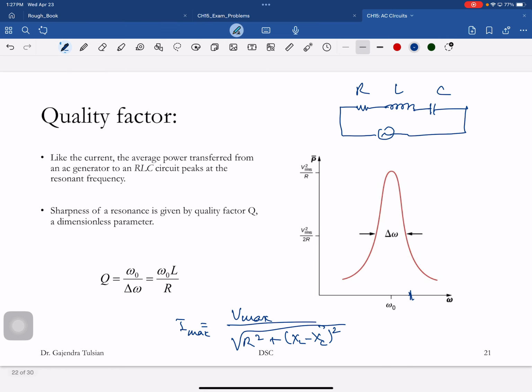Okay, so for high quality of the circuit, the peak is half as wide. Okay, the peak is sharper. And you see the width of the peak, the smaller the R, the smaller the width. Okay. The problem with having small R, and so large currents, is if you pass too much current, things will burn. Okay.